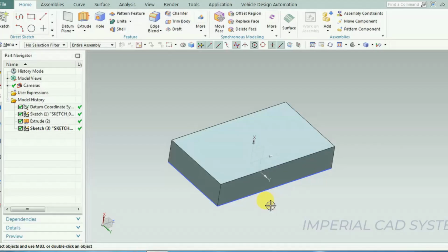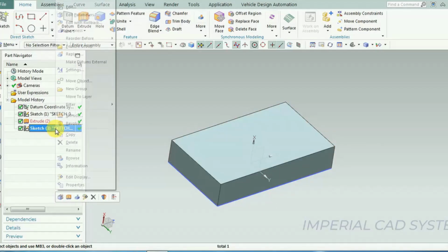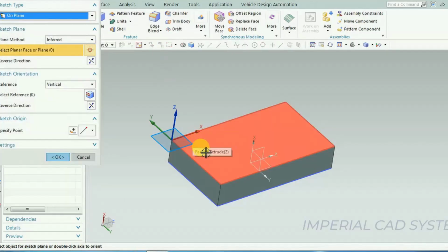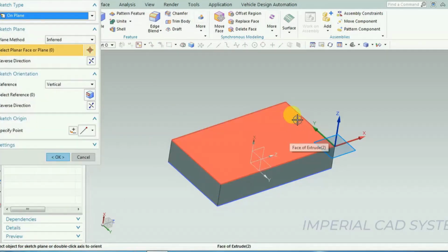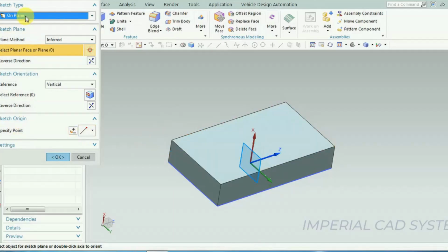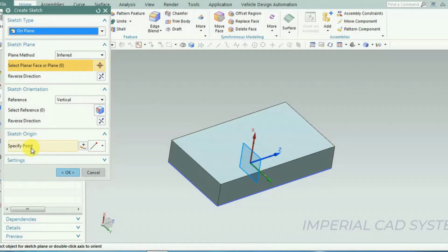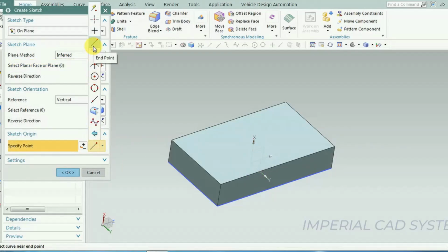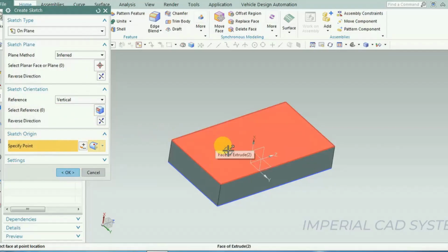Once I get out of the sketcher, then we have the option. I will show you that. Then in the sketcher itself, see, what do you call this origin? Origin is moving on 4 endpoints. I want wherever I select, the origin point should be placed there. In that case, here in the sketch window, select specific point. Here is where the point should be placed. There are different options like inferred point, cursor location, existing point. Then select point on face, because I want to select a point on the surface.